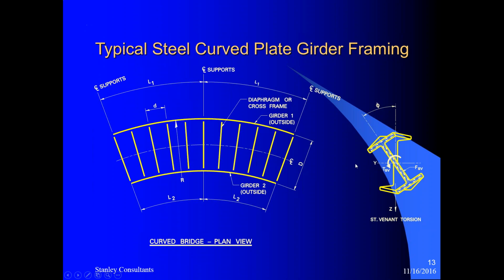Since plate girders have very small torsional stiffness, the girder needs to deform excessively to resist these torsional forces. That's shown here, and often this distortion is unacceptable, and in many cases the section will reduce its load carrying capacity, and sometimes it will buckle.